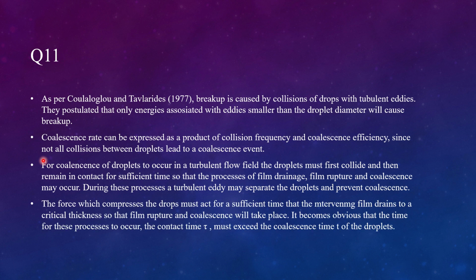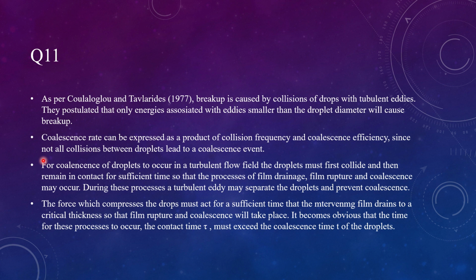The force which compresses the drops must act for a sufficient time that intervening films drain to a critical thickness so that the film rupture and coalescence will take place. It becomes obvious that for these processes to occur, the contact time must exceed the coalescence time of the droplets.